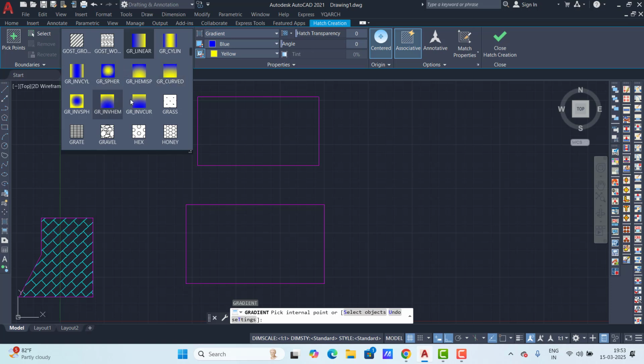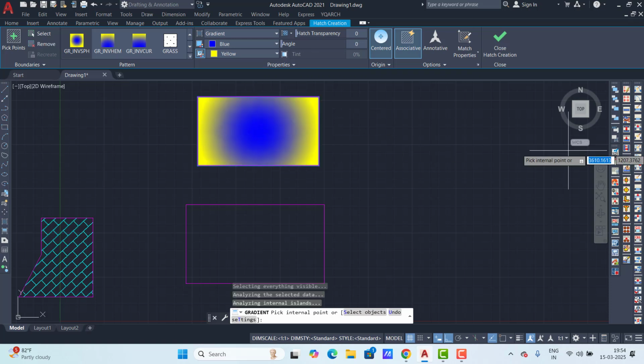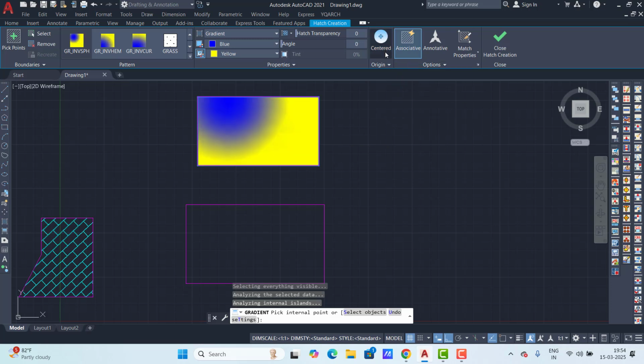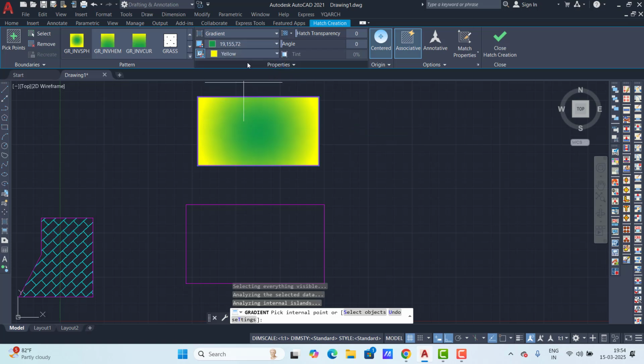Now select the move command, select this surface and just move. Select this surface and move. Select this surface and move. You see here, with the boundary command we have created four separate surfaces. My original object is kept the same.